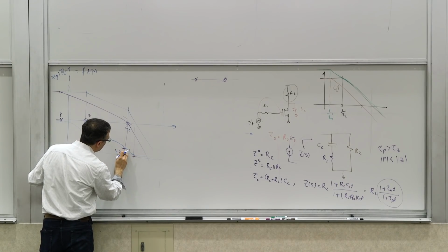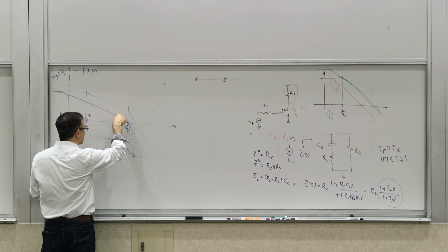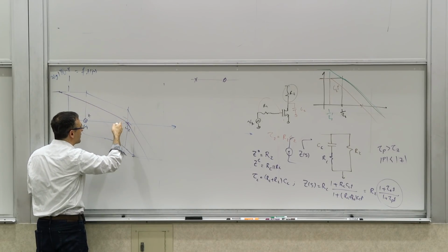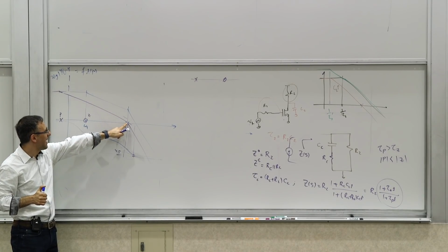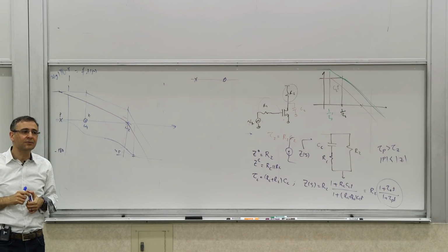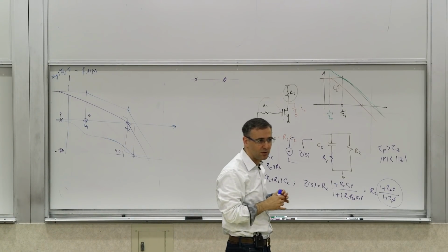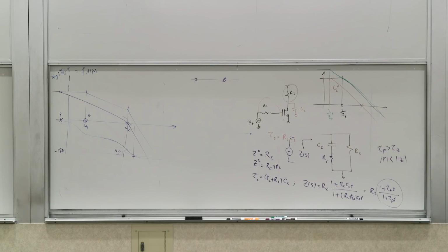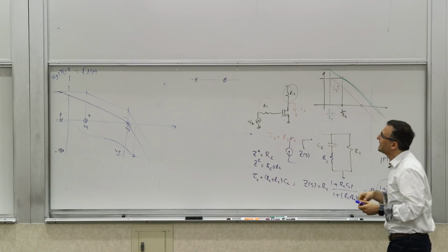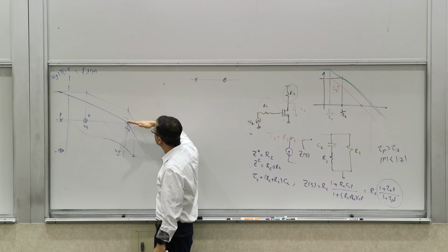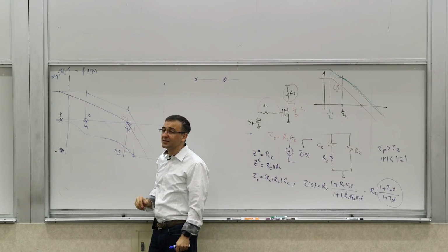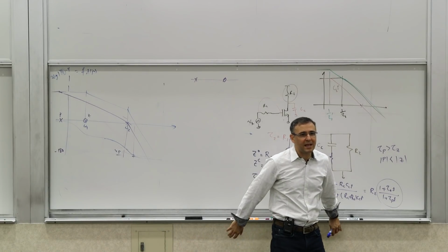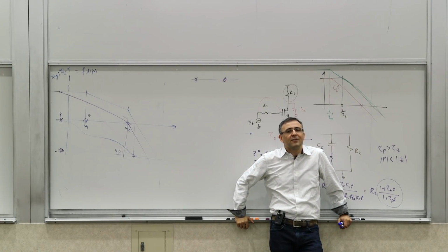By the way, if we do this, do we get more? So let's say I make this asymptote hit omega 2 exactly at that point, at 1 unit. So you have a unity gain for this thing at omega 2. Would we get more than 45 degrees of phase margin or less than 45 degrees of phase margin if these were the only two poles? What do you think? And why? If we did this, we are making this asymptote intercept the x-axis at exactly omega 2. Would we get more phase margin than 45 degrees or less?